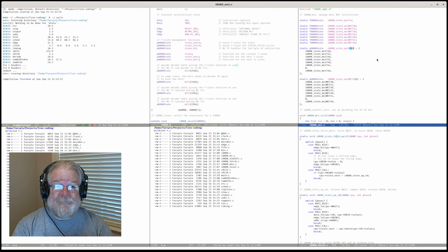Okay, so MVI init. When we call it, it's a destination register that we get handed. And for each destination register, we're going to say M2T3 is MVI M2T3 of SSS. Boom, there we go. That picks up those 8 functions. I am going to write into M1T4 is going to be I8080 state. Oh, we need an M1T4 for that as well.